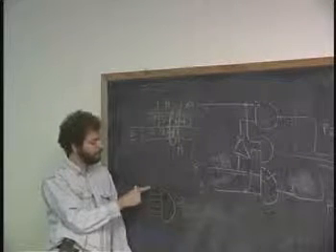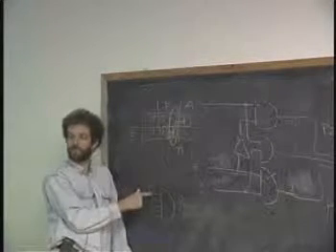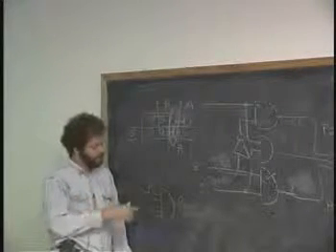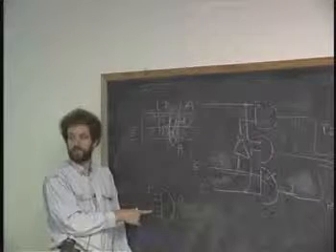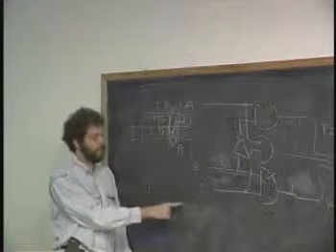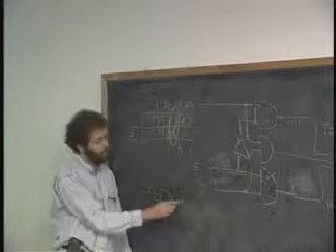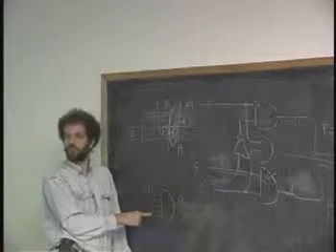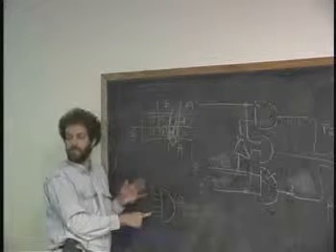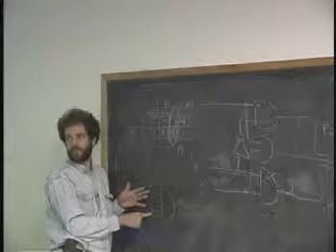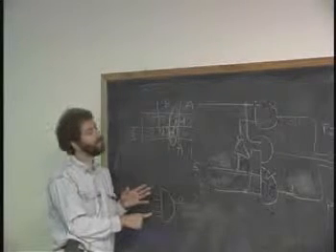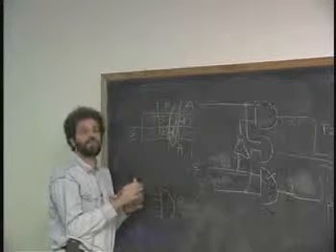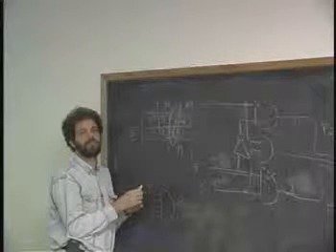Because here, this one's a 1 and this one's a 0. It's the only one that changed. The rest are constant. Because that's the conditions under which we're operating. At least one of them was held at a 0 and did not change. So did this output actually change between these two states, or did it guaranteed stay low? If I have an AND gate and I hold one of the inputs low all the time, these things can wiggle up and down for all they want. Nothing's going to happen. So, as strange as it may sound, a sum of products implementation can never generate a 0 to 0 hazard. Okay?